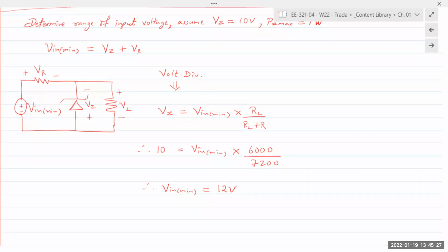Whenever we say military grade, more often than not it refers to extreme temperatures, really hot or really cold. It refers to diodes and electronics because the voltage actually shifts. The Zener voltage or the diode voltage will shift depending on the temperature. And if you remember the diode Shockley equation, that temperature change is linear. It's actually linear. I could go back in there, but I have to find a slide.